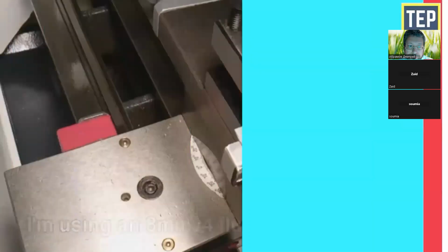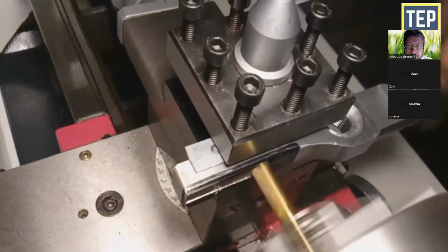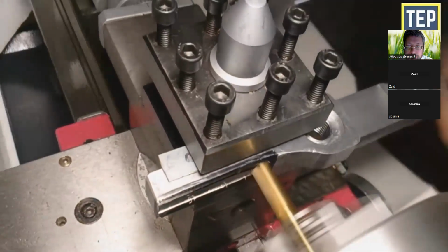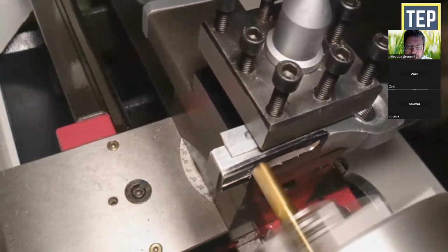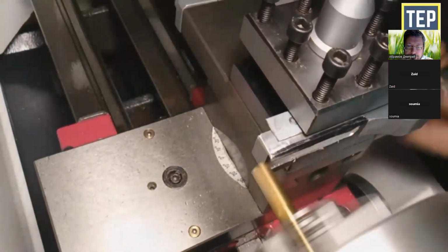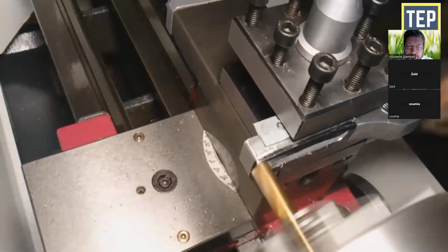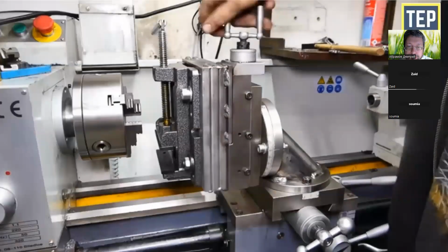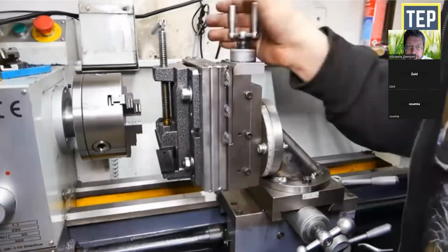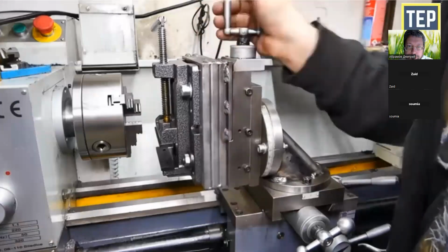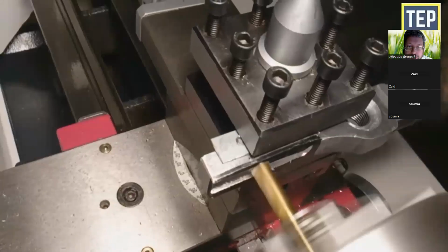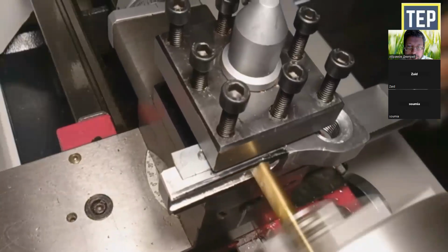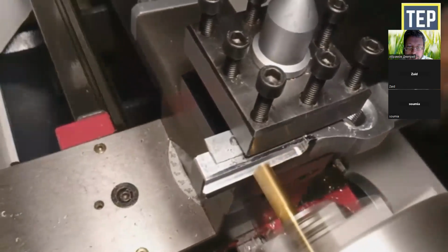Now let's take a look at the milling operation, which is done by using special attachments on the lathe. Milling is the operation of removing metal by feeding the work against a rotating cutter having multiple cutting edges. For cutting keyways or grooves, the work is supported on the cross slide by a special attachment and fed against a rotating milling cutter, held by a chuck. The depth of cut is given by vertical adjustment of the work provided by the attachment.